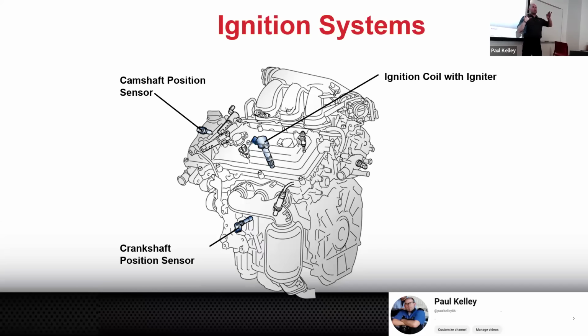So some of this we'll get into a little bit more, but overall, if the problem's in the coil, we spark check, we switch, whatever. But if it doesn't move, then we're like, all right, cool. That misfire could be a fuel problem, an injector issue. It could be a low compression issue, right? Which is why I would go to the spark tester. If you pull the coil out, you hook up the spark tester, and that coil doesn't spark, boom. We know for sure that we're dealing with a no spark issue. But why? It's not the coil because it didn't follow. It's going to have to be an issue on the primary ignition.